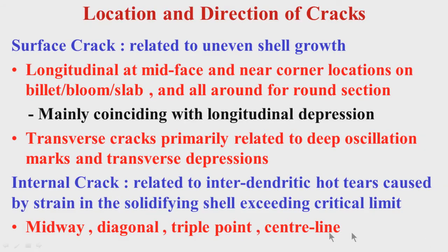In that area you apply pressure, some reduction in thickness, not suddenly but slowly in steps. There is a gradient of pressure development at the final solidification front. In that process you can reduce the intensity of defects at the center line, whether cracks or pronounced segregation.